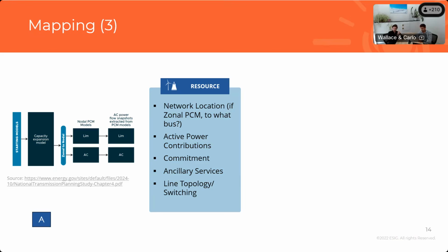Yeah, thanks, Carlos. So he's talking about sending out the whole 8760 hours of the results of his resource plan, which is a cumbersome thing at best from a transmission planning perspective, where I'm mostly thinking about snapshots. But one of these initial efforts is mapping and bringing what we consider to be the active power dispatches of all of these different devices, and then keeping them and representing them within their generation asset configurations in these transmission planning tools, like an AC power flow steady state tool. It allows me to look at the operation of those different assets across the system to better understand when there might be at-risk periods based on screening activities.